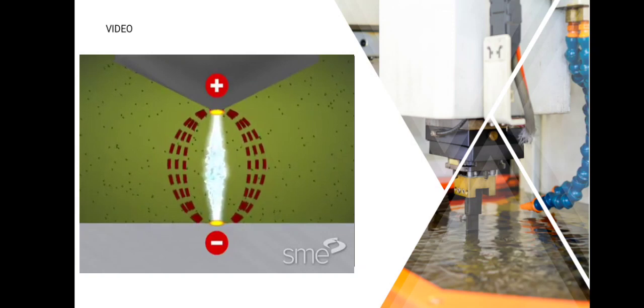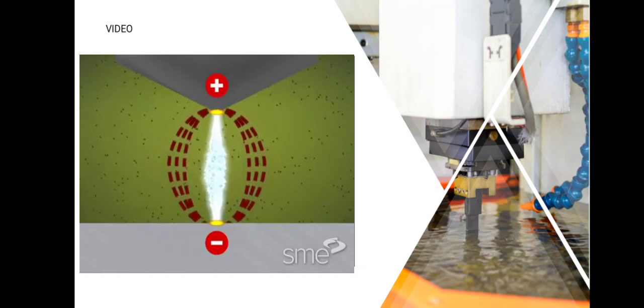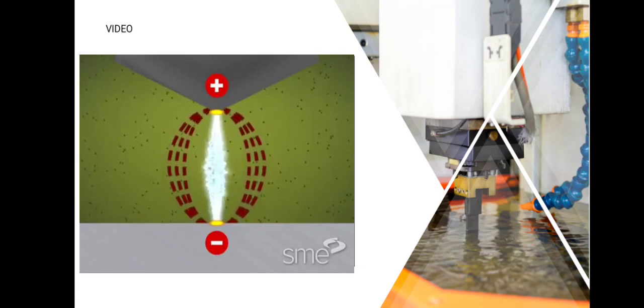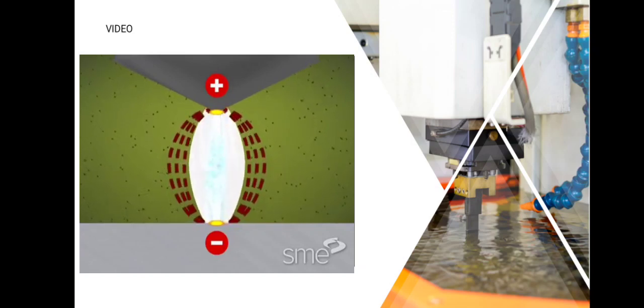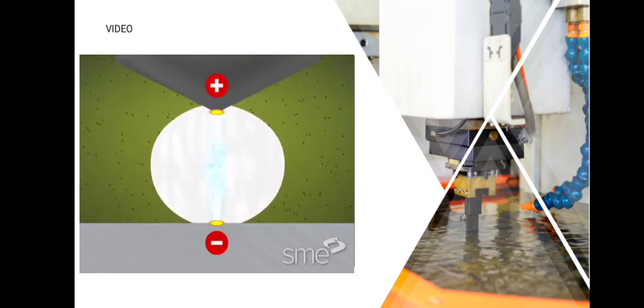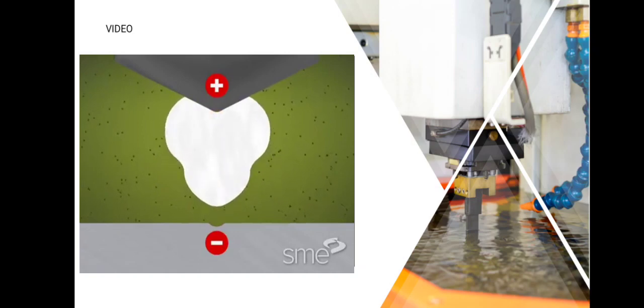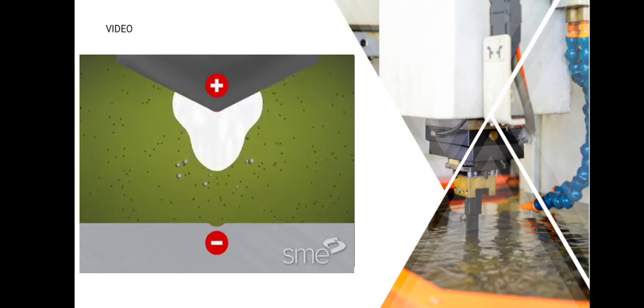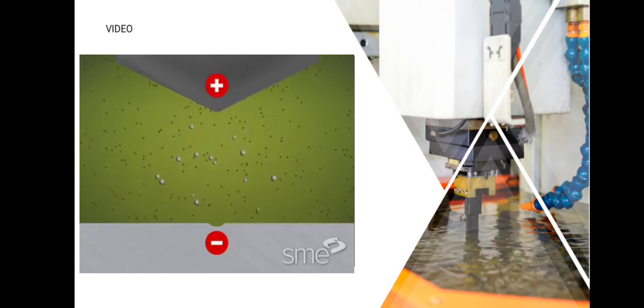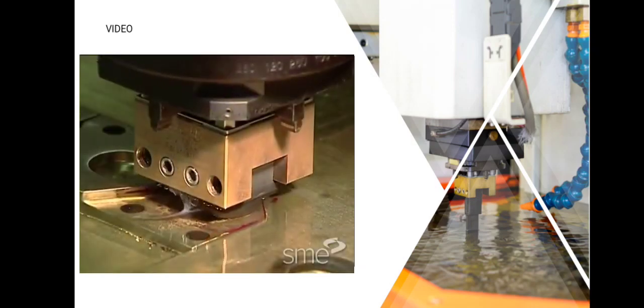A small amount of material melts and vaporizes from the electrode and workpiece at the points of spark contact. A bubble composed of the gaseous byproducts of vaporization rapidly expands outward from the spark channel. Once the pulse ends, the spark and heating action stop, collapsing the spark channel. Dielectric fluid rushes into the gap, flushing molten material from both surfaces. This EDM residue consists of small solidified balls of material and gas bubbles.